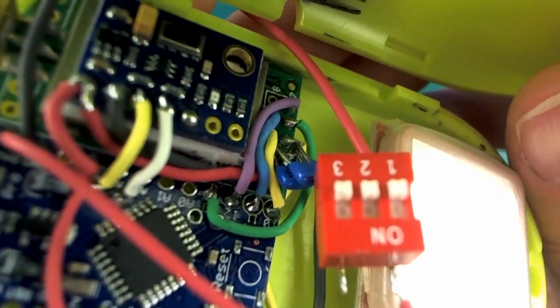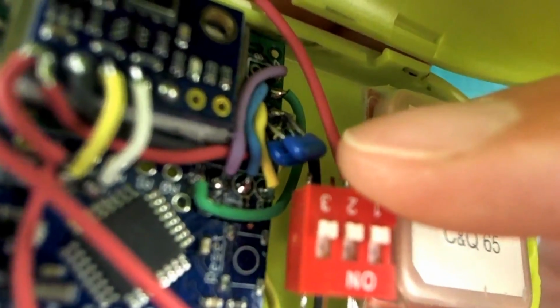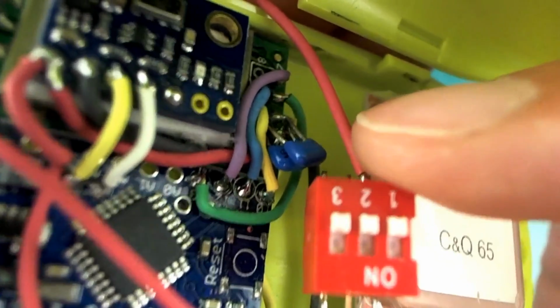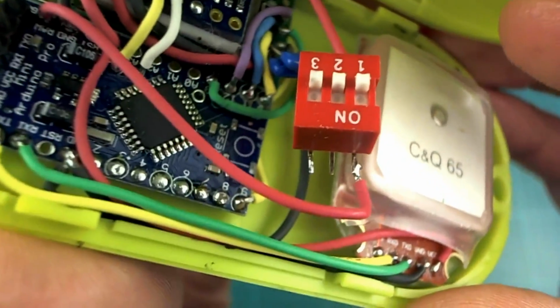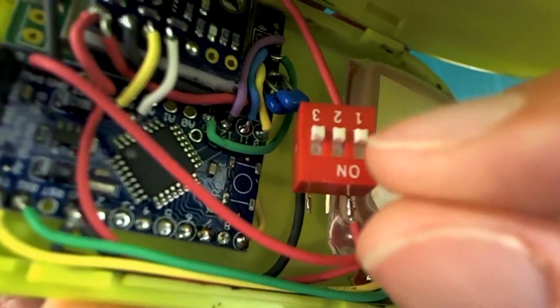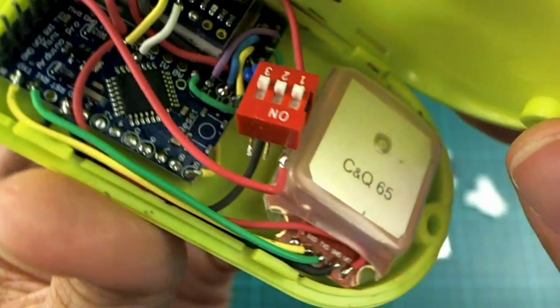And I have a couple of capacitors on there across the power for these. Probably not really necessary to have two, but it's been working really well with those two. I think one's a 10 microfarad and one's a 0.1 microfarad, and that works really great. I just have a little switch here to turn it off and on. I just use the number 1 switch of that to do that.